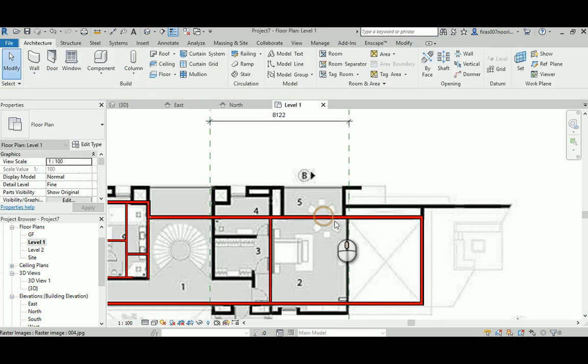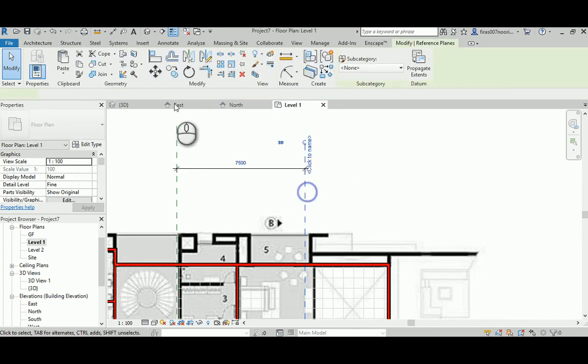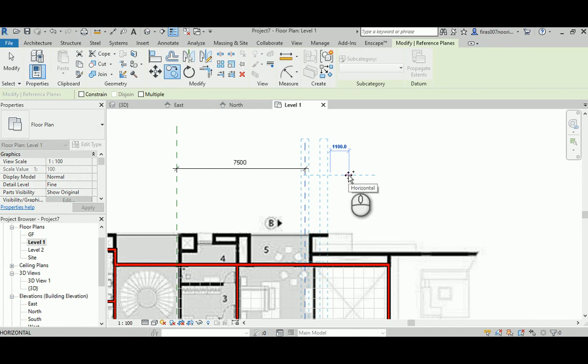I tried to do it here, with the start of the inclination and the elevation, and that's the end of it. But you can't do that, because when you cut, the plan will be higher by 1 meter. So the wall here will appear here. I found that by trying to define exactly where it is, and I found that it should be 7,500. So when it goes up by 1 meter, the cut area of the inclined wall will be here. Anyway, you'll understand that better when I just draw it in 3D.